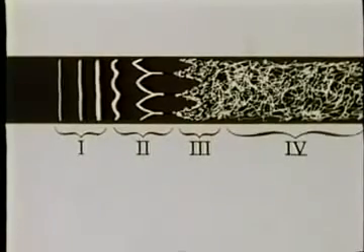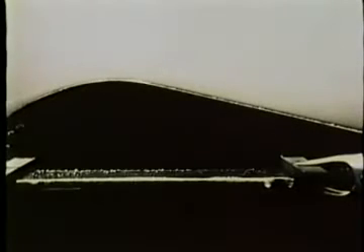Here, the exact position where growth of two-dimensional disturbances begins depends on random small-scale fluctuations in the flow, and therefore varies with time in a random way. This boundary layer around a channel bend is made turbulent by placing an obstruction in the layer upstream. The obstruction stimulates the naturally occurring processes and hastens the onset of transition. The flow here is all downstream.